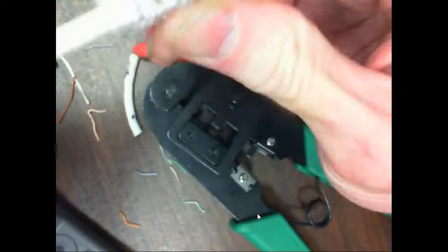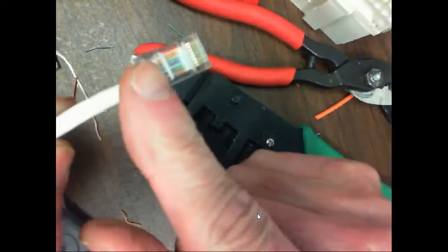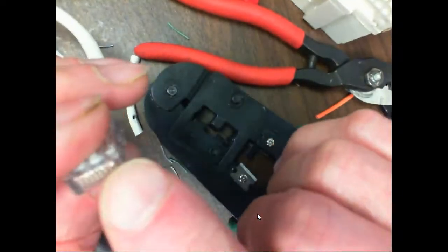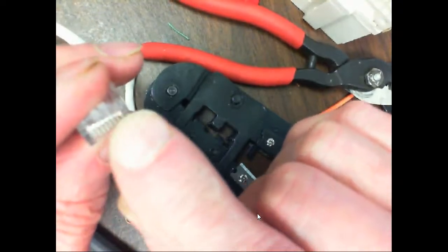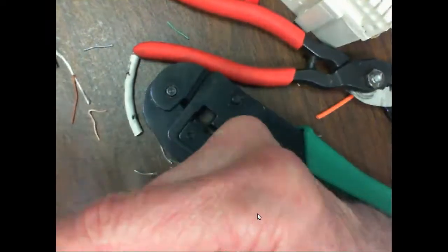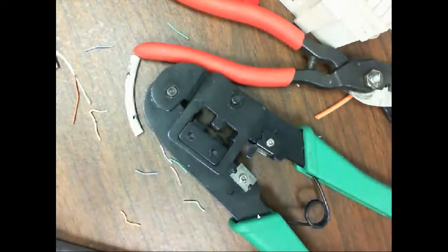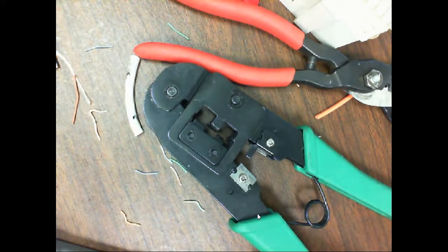And then I've got my connector on there. So what I've done is I've crimped it in the jacket. I double checked my code. I looked at the front and I saw what? 8 little old copper dots right there, which means I got it all the way in. Then we crimp it down, and this is a B. This is the 568B. Y'all see how we did it?